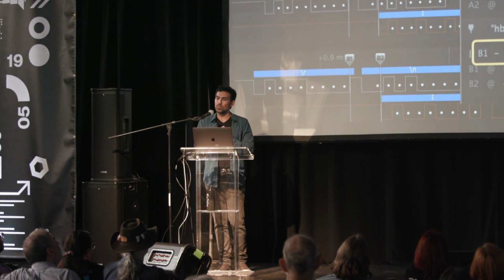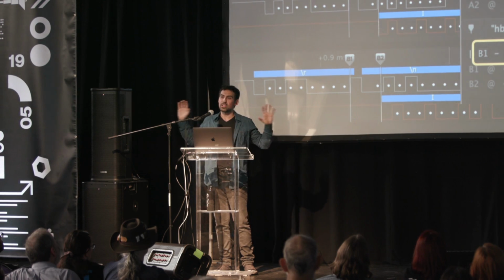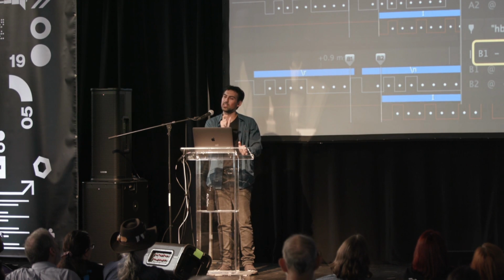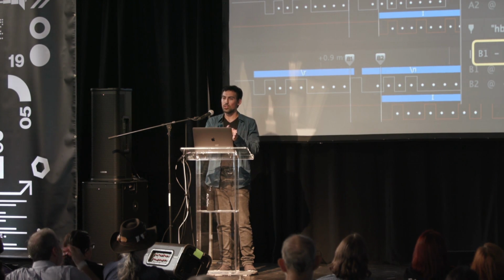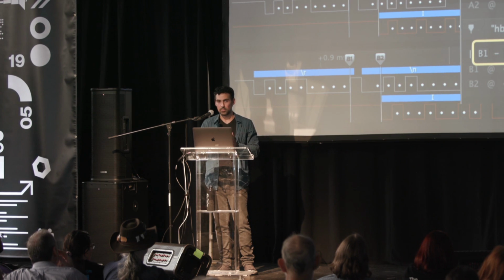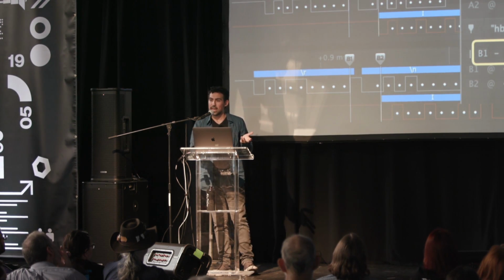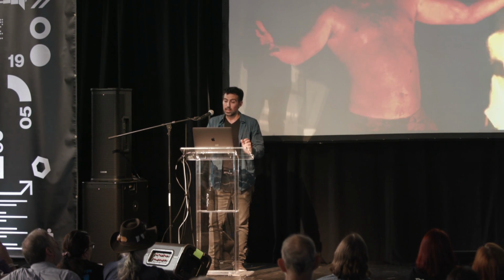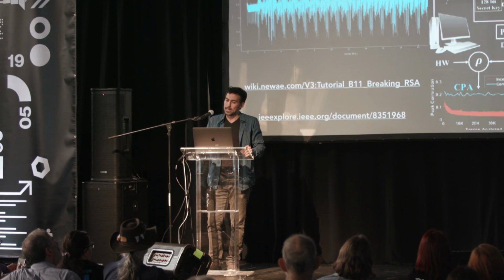And all you have to do at that point is then go through all of your characters. So instead of brute forcing the entire key space, you're only brute forcing the first character and saying, oh, this character takes slightly longer than all the other characters, and now you know what your first character is. Then you go on to your second character and you perform the same loop. This is absolutely incredible. This is a very simple timing attack. It's been known for a long time, but it's something you can do on devices today. So very exciting. And you can use side channels to do a lot of other cool stuff.